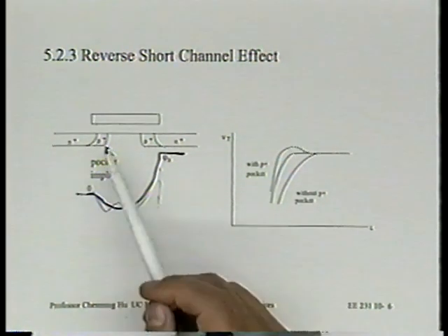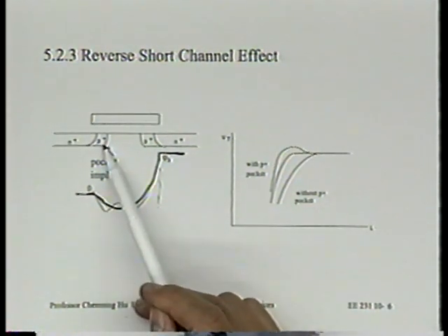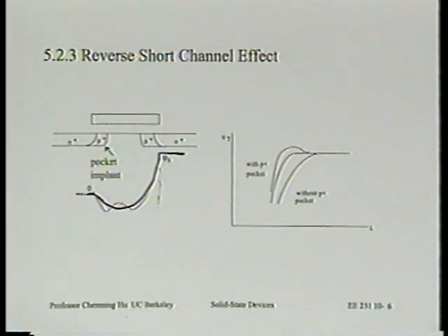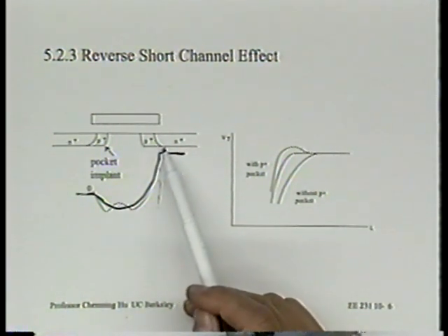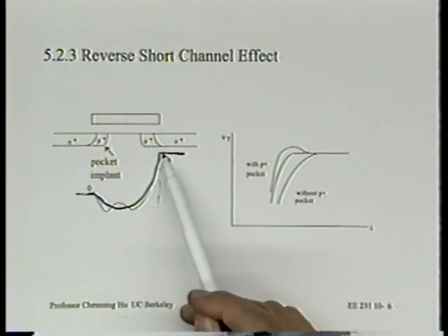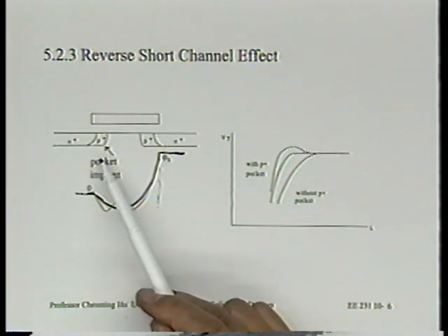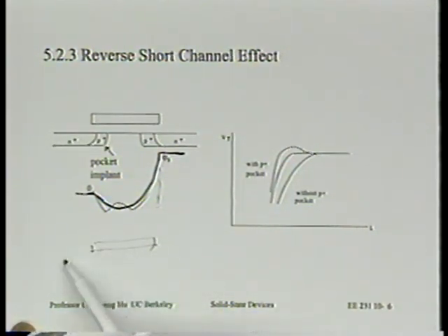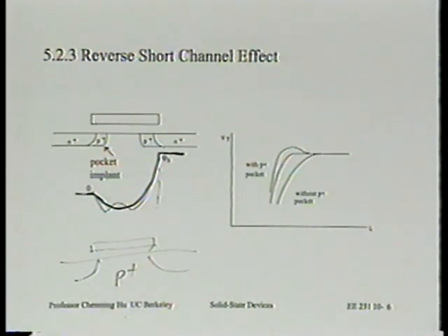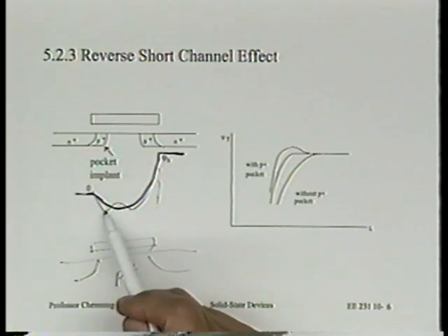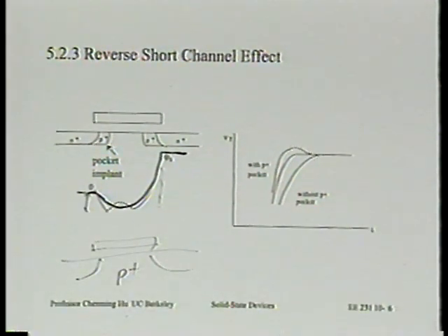So now, knowing that, we're putting in a very thin P plus region. Can you really think that this waveform is going to jump up and back down just as you go across the P plus? After all, this P plus is still falling within this transition region, the decay length, right? So instead, you have to think we're going to modify that hyperbolic sine cosine function to be more complicated. You may create 2 peaks as a result of the N plus, right? But this peak certainly will not reach the same height as a transistor with just a uniform P plus doping. You see what I'm saying? Because doping everywhere has influence on this potential profile everywhere else. And it's that final total effect, the highest barrier, wherever that may lie, that will give you the threshold voltage. You see what I'm saying? It's correct? All right?